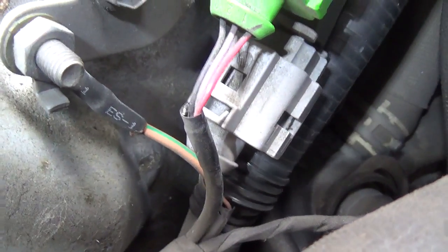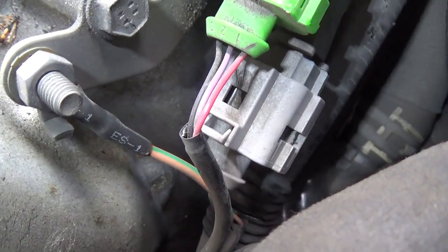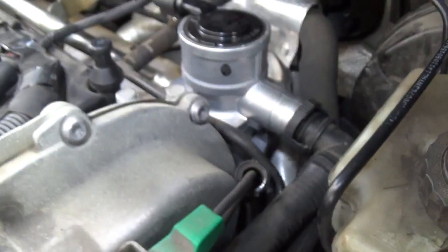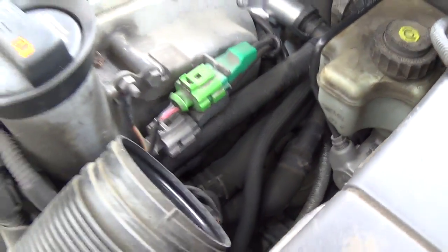But anyways, doing a visual inspection, I unplug this and I'm like, that's kind of loose. If you look at here, there's your problem. This pipe is completely torn. It's barely hanging on right there. It's just split, the plastic is completely split. I think that explains our insufficient flow code. We could tape it up right now, we can get a new pipe, whatever. It's a really simple problem. There's no electrical, it's just a cracked plastic tube, that's all it is.